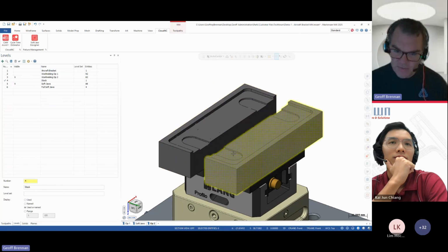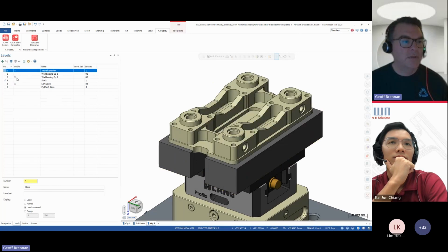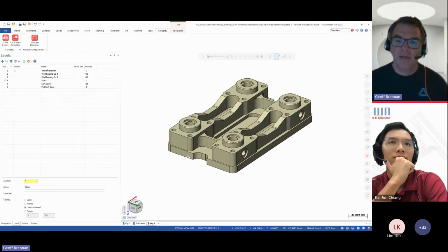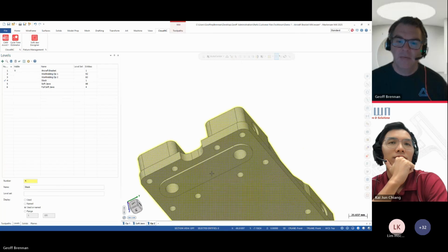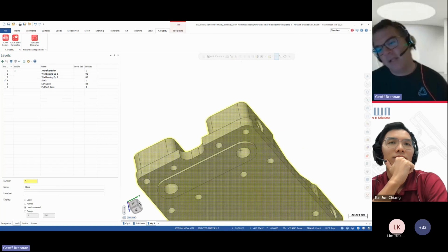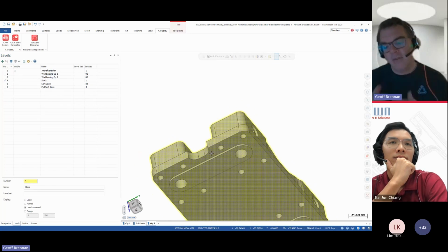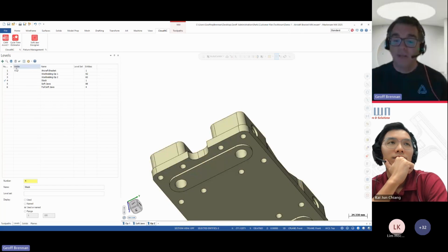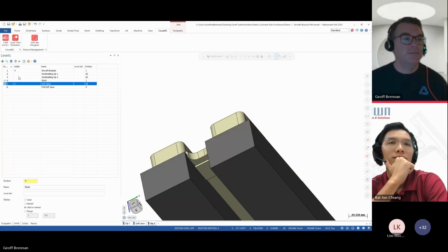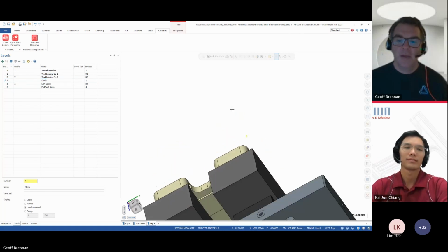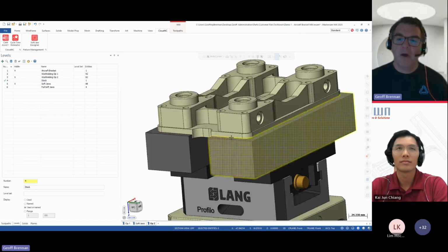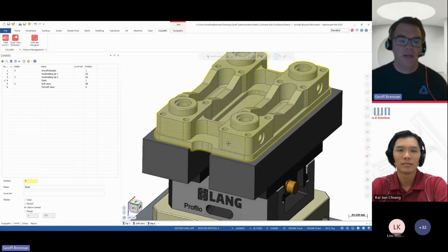And these channels here are intentional. If we look at the part itself, we have that slot there that allows the jaws to open and shut. If these were just round bosses and didn't have the slot here, we would still get that C channel as well, because we'd have to be able to open and close those. So the part geometry can be quite complex for creating the soft jaws. Okay, so we've got our op2 work holding configured and ready to go.